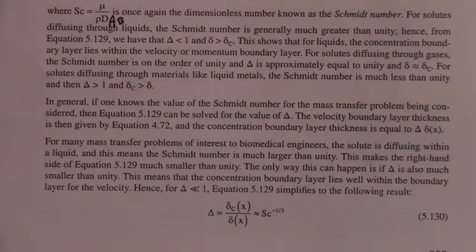Now remember that when we started talking about mass transfer coefficients and Sherwood number correlations, I was telling you how 99% of the time, the Schmidt number shows up in these correlations as being to the 1/3 power. And that 1/3 power is coming about through this boundary layer analysis that we're talking about for liquids.